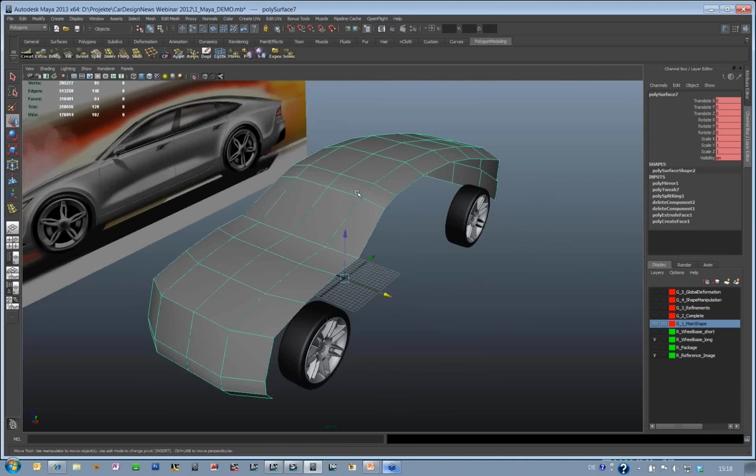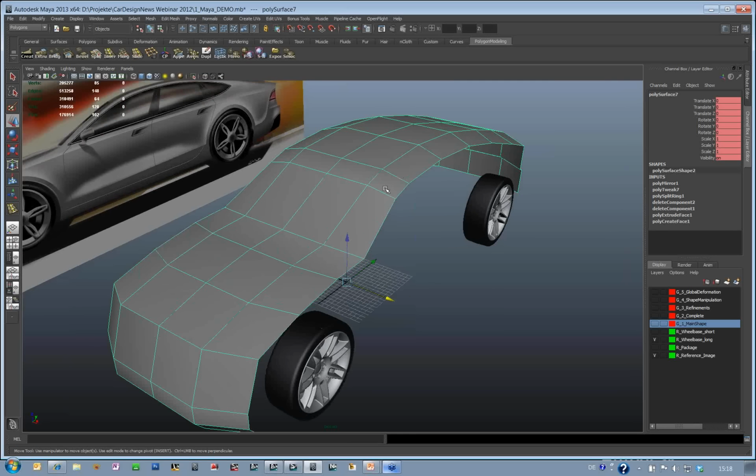Now one important feature available in Maya, during the concept modeling with the polygons, is to keep the polygon amount as low as possible. If I create too many polygons, I have a problem adjusting the geometry later. So my goal is to have as low a polygon level as is enough for describing the shape without losing my intention, my idea behind it.